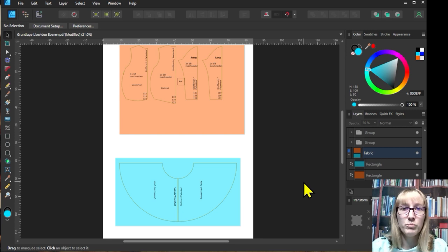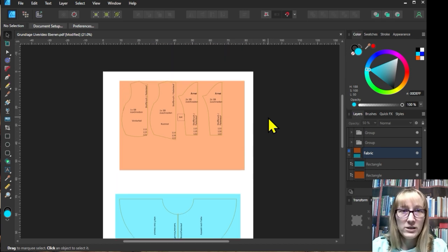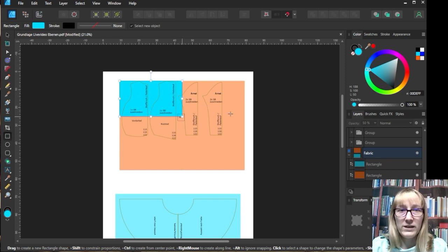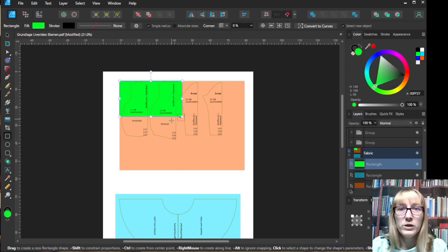If you have a small projection surface, you can now also create guidelines or helplines. These will help you later to lay out the fabric accordingly. If your pattern piece can always be projected as a whole, you don't need to do this. My projection area is usually only A1, so it is not enough for adults' pants. In my example, it's a child's cut, so I'm just improvising now. I create a rectangle for myself. The green one is my projection size. If you want to set your own projection size, you can enter the data below accordingly.